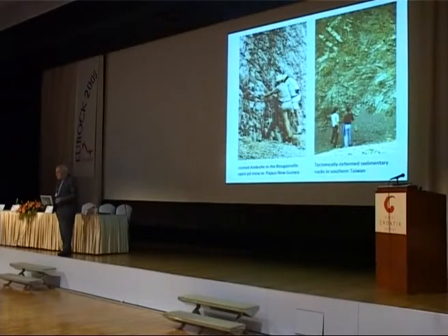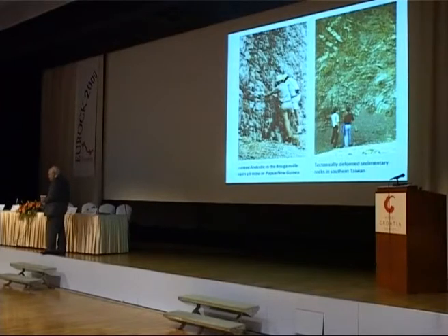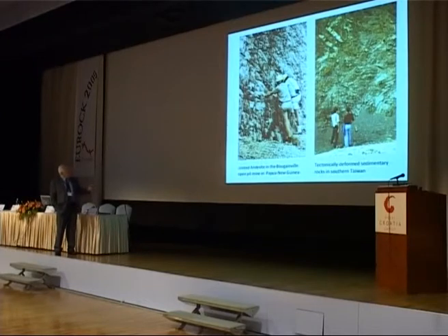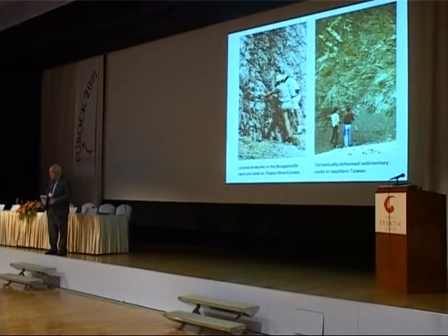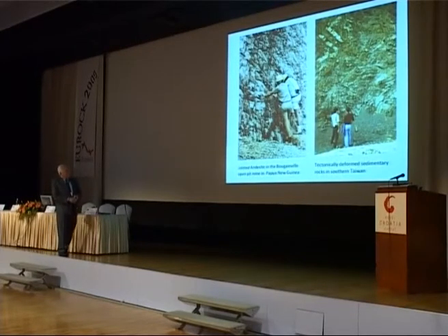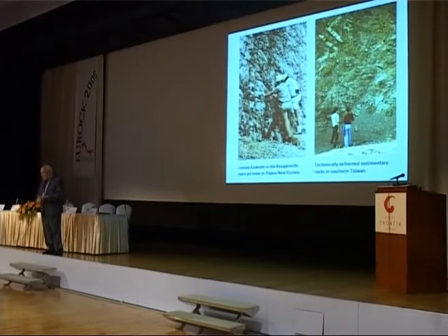Coming now to the semi-homogeneous rock mass to which these classification-based systems can apply, I start with the heavily jointed Panguna andesite, which formed the basis of the Hoek-Brown criterion in the early 80s, late 70s. And this is a very strong rock, but with something like 7 intersecting joint sets, very closely spaced. And at the time, we were looking at the design of a 1,000-meter high, open pit mine slope, and felt at that scale, this could be treated as a special kind of soil with interlocking granular blocks.